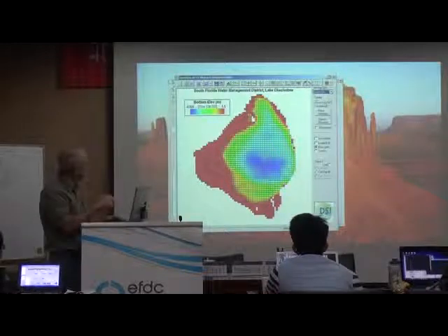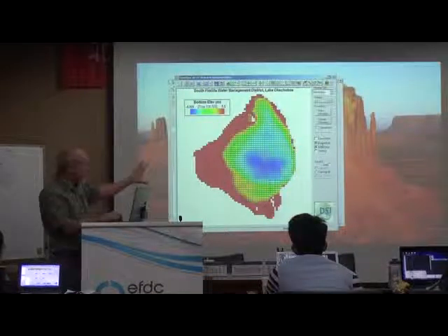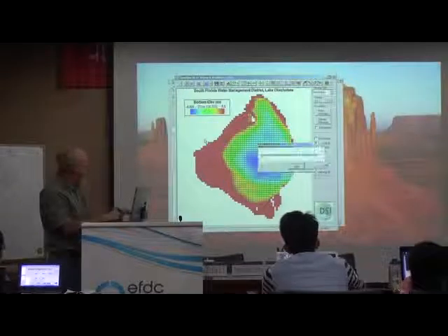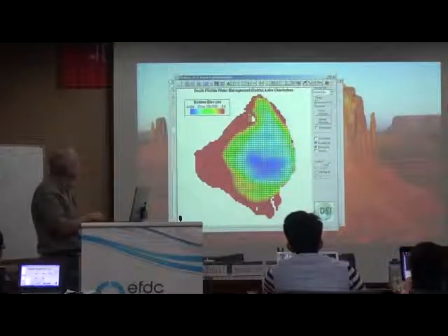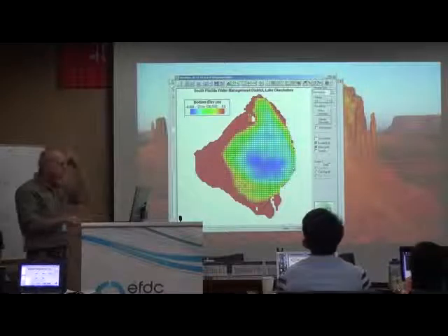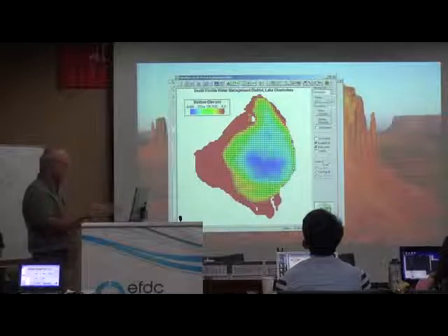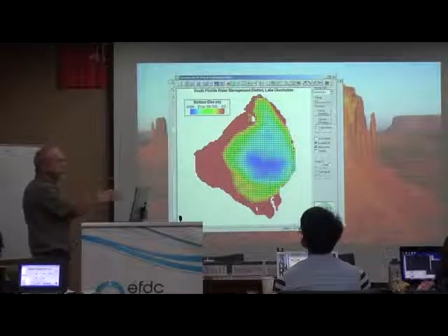It's smoother, and you've set up the grid to follow it a little bit better. You can create your grid originally in the quadrilateral, and then at any time you want, you can switch it to a staggered grid, and it'll automatically go out and add your triangular cells at your borders. And then if you don't like one particular border or another, you can just go in and edit it manually.